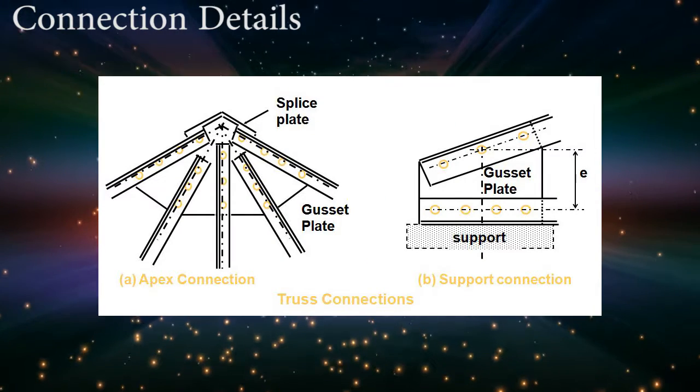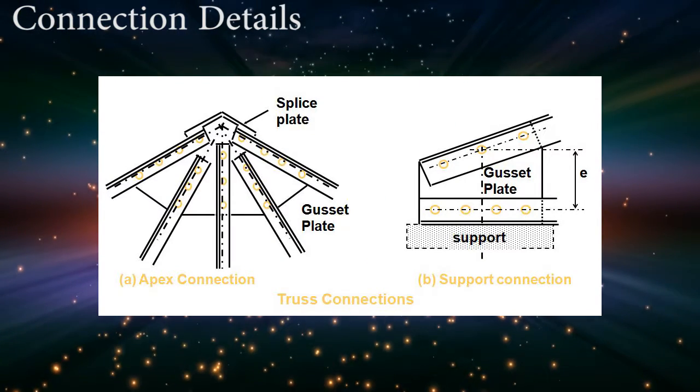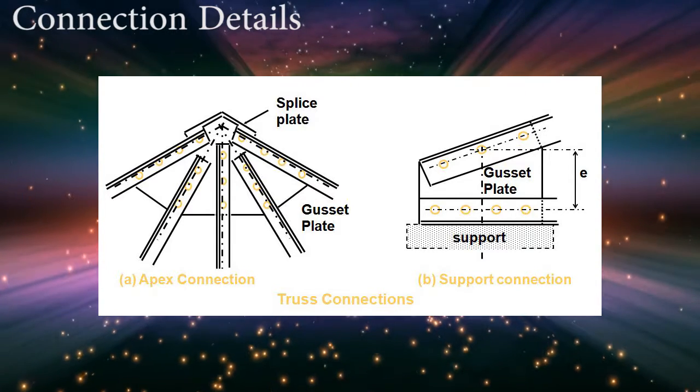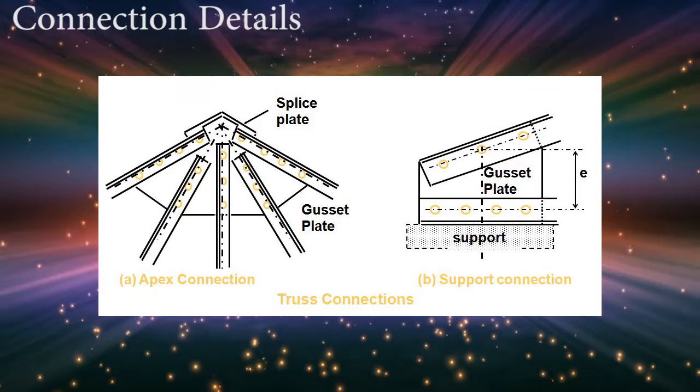Beam connections similar to beam column connections. Moment continuity may be obtained between secondary beams. Check for torsion in primary beams.